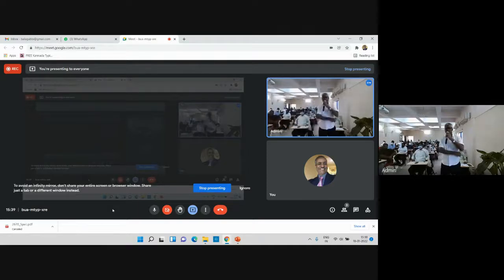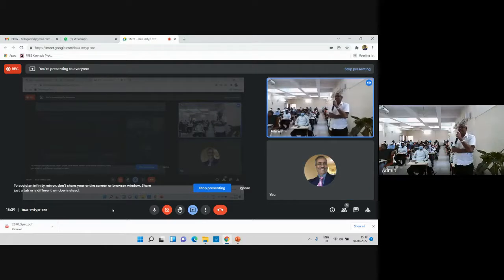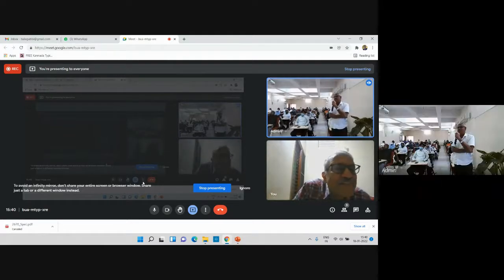Sir, thank you for your wonderful lecture on smart meters. We have a few questions regarding smart meters. We have deployed around 8,800 smart meters in our utility. We can see that the communication of the meters to the head-end system is not more than 70% at any point of time. We have different modes of communication from the smart meters to the head-end system: hybrid communication like RF mesh with PLC, and GPRS communication also. We can achieve communication of more than 70%.